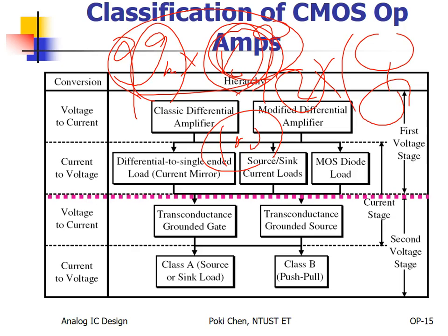The other example is, if you would not like to sacrifice your headroom, you would like to increase GM by the same number. I promise you, you need to enlarge your input transistors by 100 times.